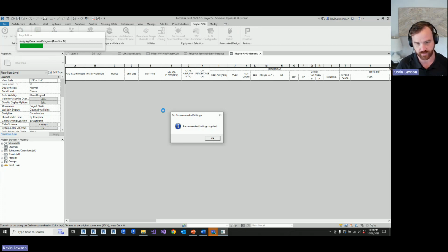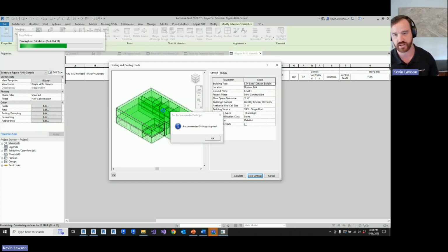If there's a room on the level, you're going to need it in your project. So it just copies that over and creates a ceiling view and a floor view so that you can look at it. Now, sometimes architects go a little level crazy. So it doesn't copy over every level, just the levels with rooms on them.